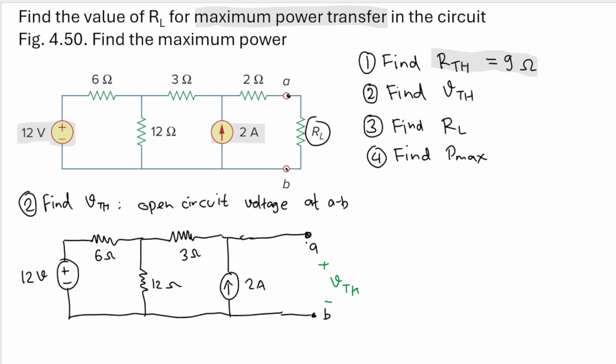Okay, and I think that's good. Now we need to do circuit analysis. How to do that? I think we need to name this here as node A. And let's set this as our ground, so the voltage here will be 0.